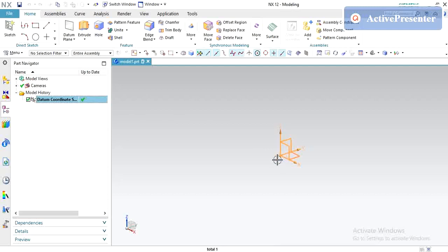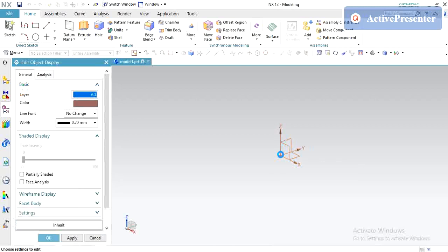Inside this one you will have one point and axis system. If you are aware of CATIA, in CATIA we will have default 3 planes. Whenever we are going to start a sketch, we will use the axis system and the point. In UGNX it is default, it is created. If you want to change the sketch position, if you update this point, your sketch and related features will move accordingly.